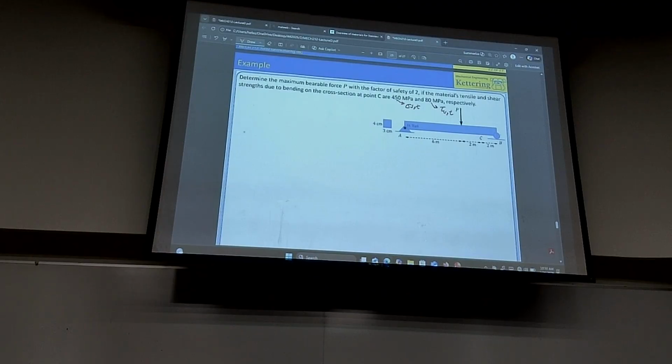So first, sigma, you said, do everything for stress. So sigma u over factor of safety, this is what we did in test 1. Equate it with sigma max, and then tau u over FS, set it equal to tau max. Again, whatever stress type is applicable, you run that like this. And in particular, sigma u comma t in this case applies.